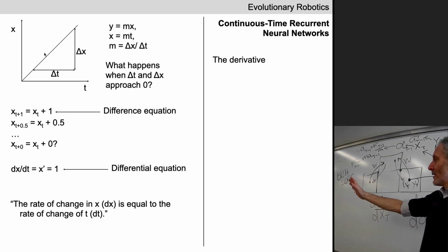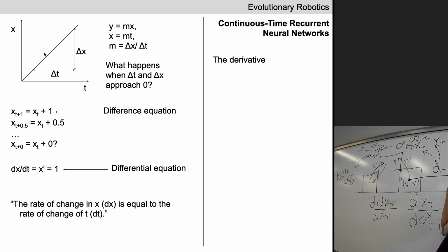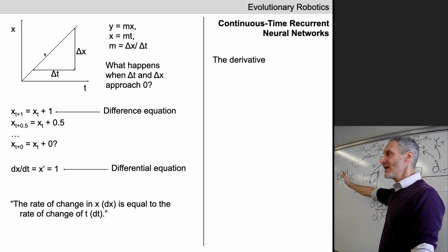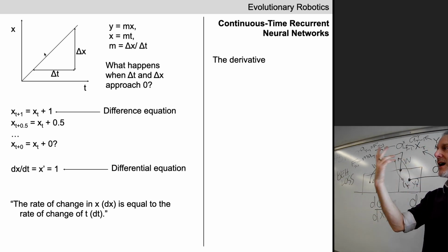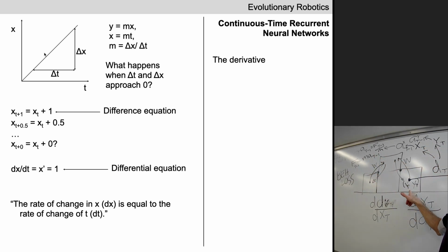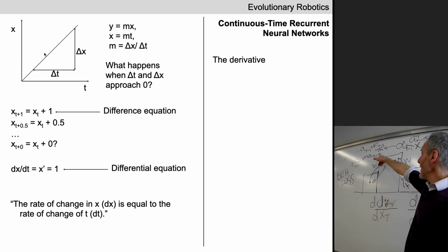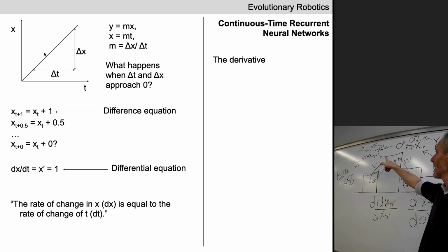To review, we've done 1,000 time steps of simulating the robot, and now we've gone backwards. And the physics engine has calculated all these gradients. It's then up to you as the programmer. What do you want to do with those gradients? Let's have a look at M for a moment. This is the mass of this object. It might say, for example, if you wanted this to have been smaller, M should have been a little bit bigger.